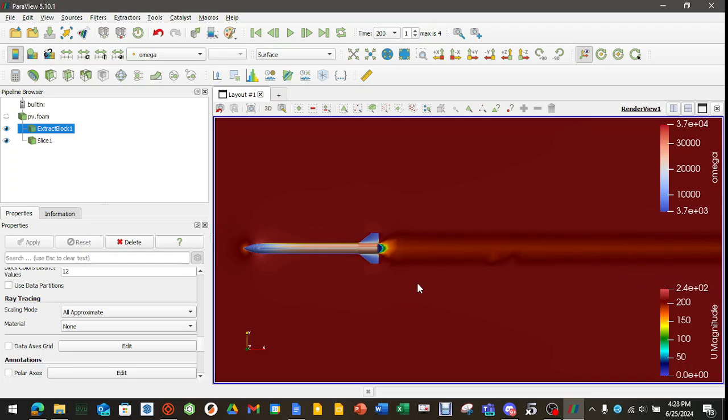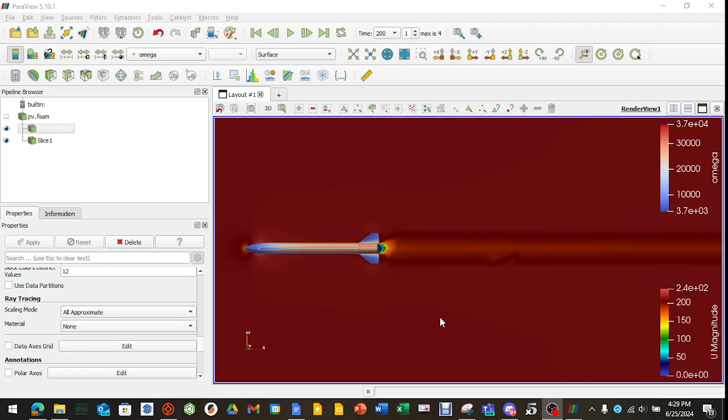Now we can do the same thing, and as we increase that velocity, so use the exact same model and then increase the velocity to a lot higher. Let's say 420 meters per second. So as you increase that, like I said, to 420 meters per second, visuals are going to change. So I paused the video, went ahead and did that, and make sure you change your reference pressure or it won't work.